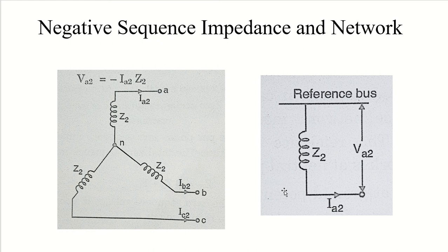When it rotates at double the synchronous speed, current at double the stator frequency will be induced in the rotor field as well as in the damper winding, right? So the negative sequence mmf will be alternately present with reluctance of both direct and quadrature axis, and because of that, the rotor surface will be swept over.